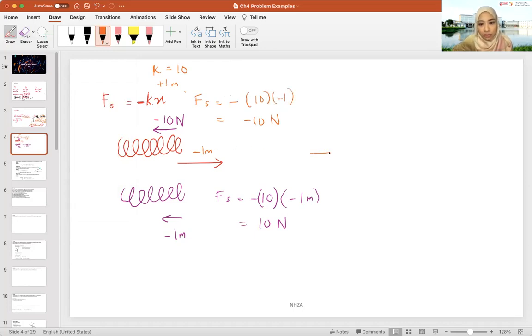So what does that mean? So positive ni negative, maksudnya sini positive kan? This means that I would get an elastic force of 10 Newton. And I said to the right is negative, therefore to the left is positive. So I know that this guy is to the left by 10 Newton. So the direction that you defined earlier on tells you the direction of the elastic force. It doesn't matter if you're saying to the right is positive ataupun to the right is negative, asalkan kena define. Kalau tak define, you wouldn't know the direction later on. So defining your extension as positive or negative is important.